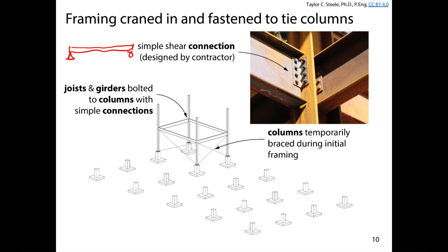The angles are oftentimes either welded or bolted to the beam first. The holes are pre-drilled in the column. And so when they lift this into place, they'll bolt it to the face of the column or to the web on the other side here. Okay, so they'll make a little square connecting the 4 columns together and brace it so that it's stable to continue working on.